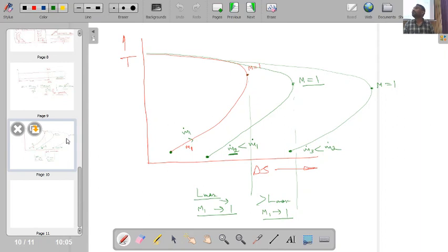But if you are having the supersonic flow situation, then what will happen? When molecules feel that they are getting some additional length, they will try to pass this information towards the upstream direction, but our flow velocity is higher than the speed at which molecules are transferring this information to the leftward direction or upstream direction. So what will happen? These molecules will actually pile or coalesce at some particular location, and there they will form nothing but a shock wave.